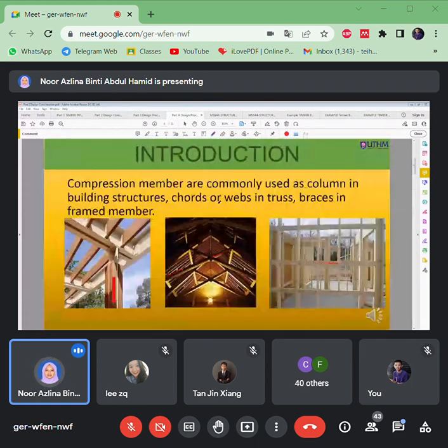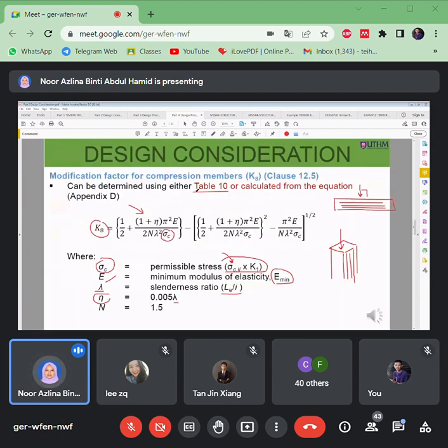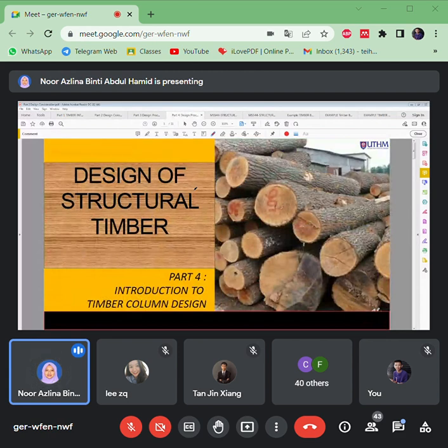It looks complicated, right? Because of many references you need to make in the tables. But I can say that if you really understand, the timber design is actually quite simple compared to concrete, because it is just a natural construction material. All the strengths just refer to the beam sections. There is no reinforcement inside it, just the strength of the timber according to its grain directions, the strengths parallel or perpendicular to the grain directions. So that's it for the timber.